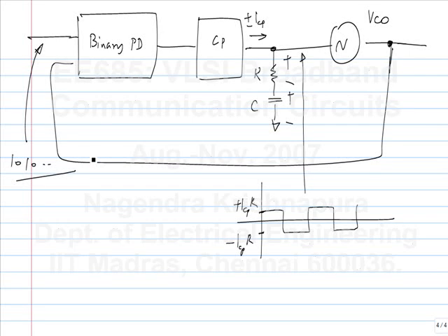Yeah, first of all, its average frequency will equal that of the input. Okay. That's why the phase detector gives you 0 on average. That is, in some periods it will give you 1, in some periods it will give you minus 1. Okay. So what will happen to the edges of the clock? Yeah. So one period it will be early, next period it will be late. And how much will that be?